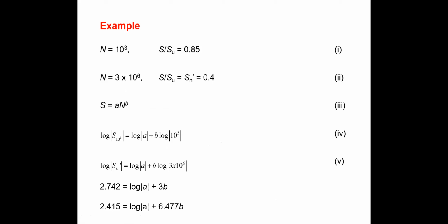Even though we change the stress range or number of cycles, the SN relation is not going to change for the material. Okay, so that's why we are going to find out the relationship between S and N. Then if you substitute S in here, you can find out N if you know a and b. That is capital N, the total number of cycles to break with this stress. Are we clear? Yes, clear.